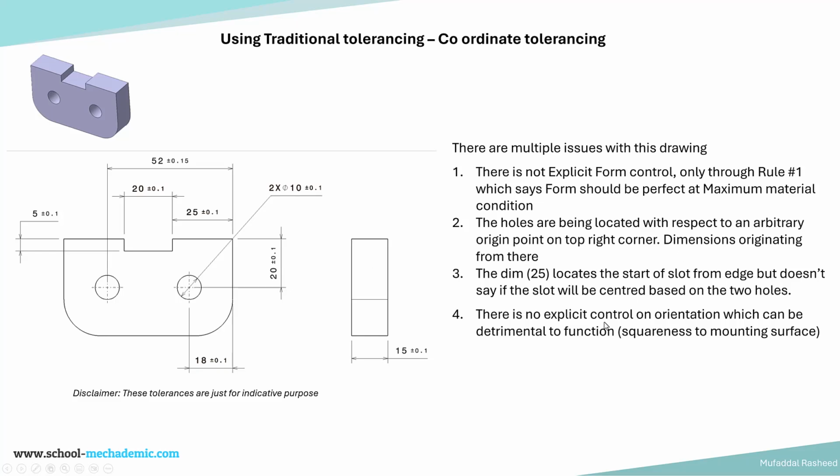There is no explicit control on the orientation of the holes as well. The holes and the slot, there is no control of orientation of the two features of size, which can be detrimental to the function as well.